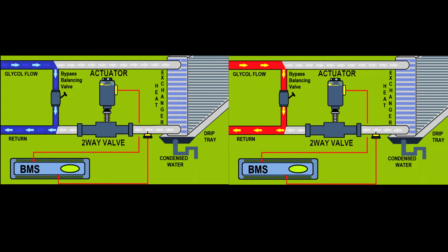The actuator will act on the valve, and the heating agent will be restricted, and it will not pass through the heat exchanger. And then both of these heat exchangers, the cooling and the heating, will be on standby. Guys, I hope you know there's a bandwidth in which both of the units will be on standby mode. That is the dead band.